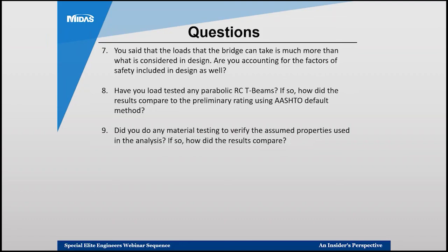However, we design for it. So in other words, you design for 100 kip feet, whereas the actual moment under this specific load, let's say, is 60 kip feet. So you have those additional 40 kip feet just coming from your method of analysis. Other than that, all your safety factors, like the phi factors and the ultimate load combination factors, everything else is the same. I meant that they can take even more based on your analysis assumption.